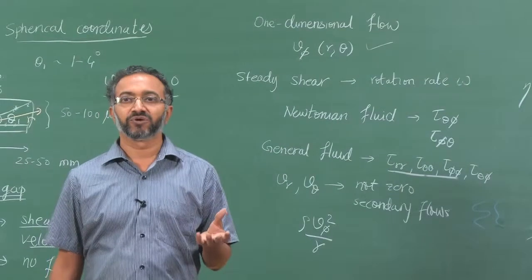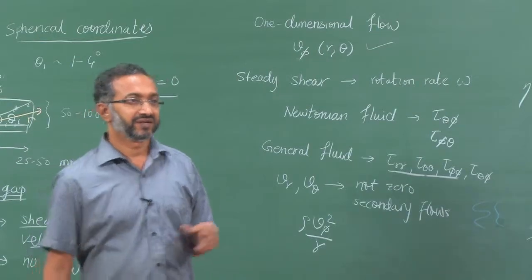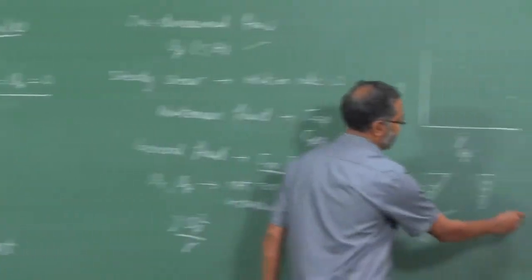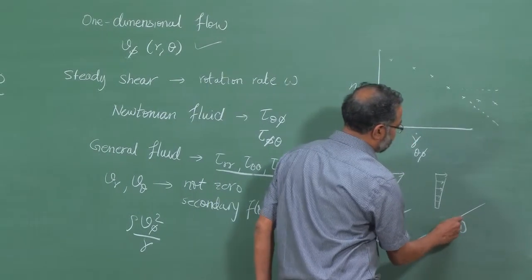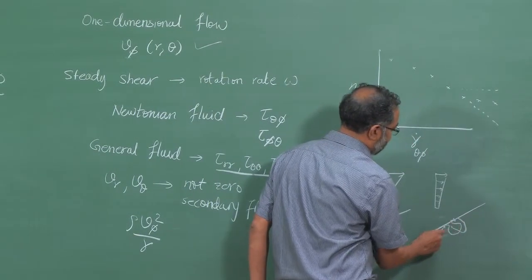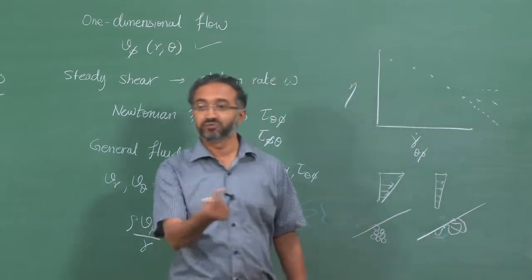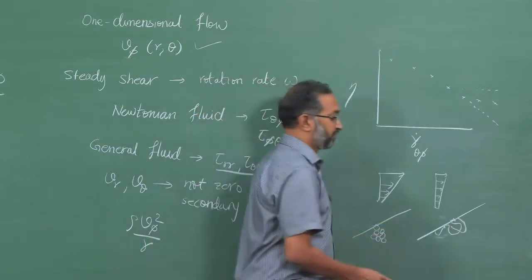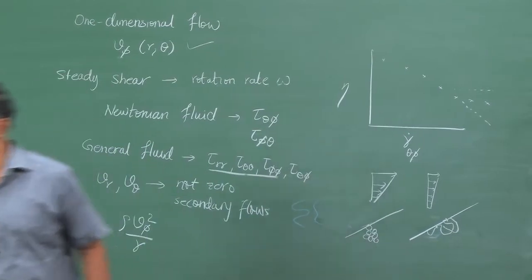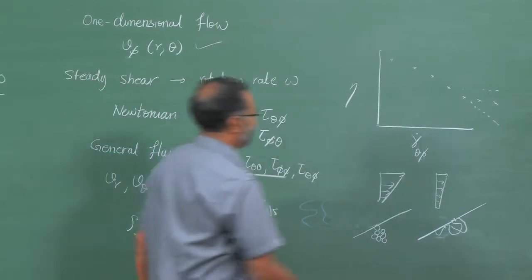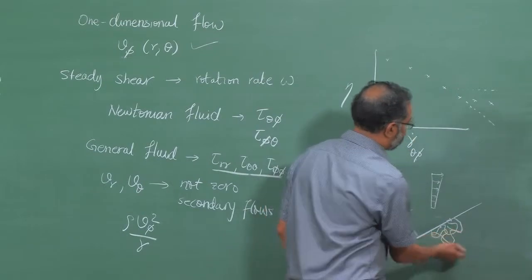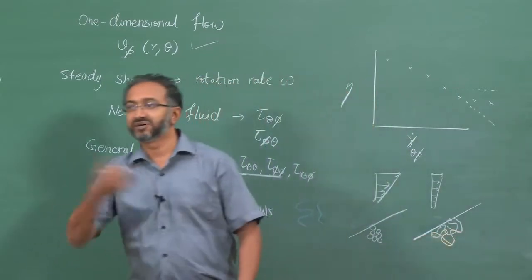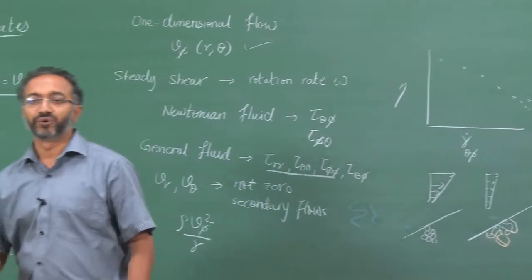Similarly, in case of macromolecules this is also possible, if you have an entangled melt. The polymer will be adsorbed and interacting with the top surface, and therefore it will move along with the cone, but this polymer is also entangled with other molecules, and the entanglements will cause the polymer to come off from the cone.